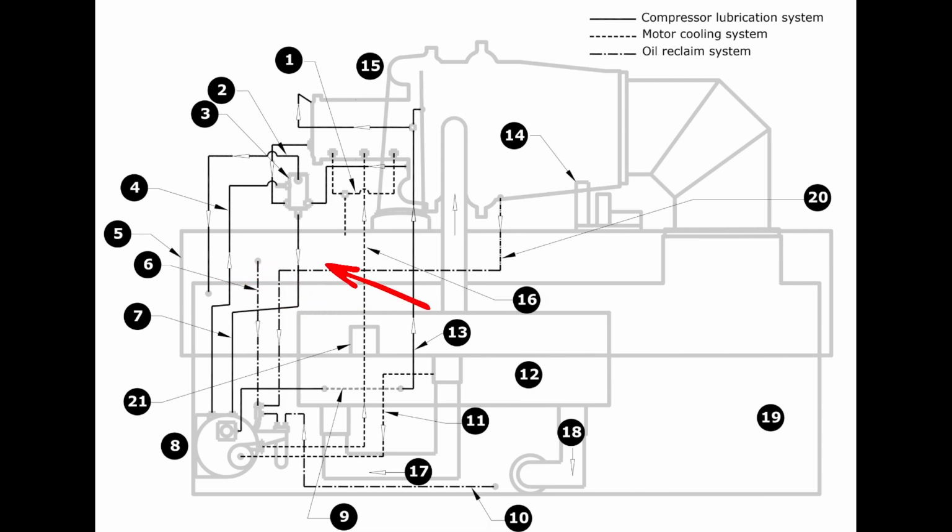So it's just a way of trying to control how much refrigerant we allow into our tank assembly, and what kind of pressures we maintain here. Because a big part of how we control our oil pump is based off of pressure differential. So if we're allowing this tank to build pressure, then we're going to cause differential issues with our pump being able to keep the compressor lubricated as well.